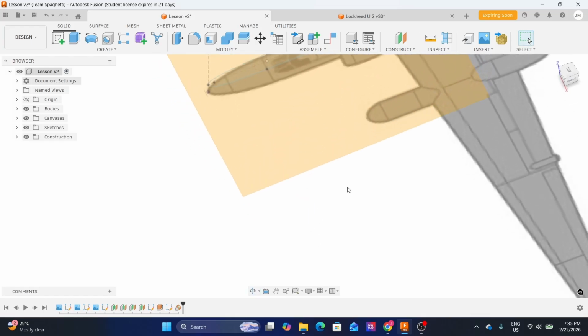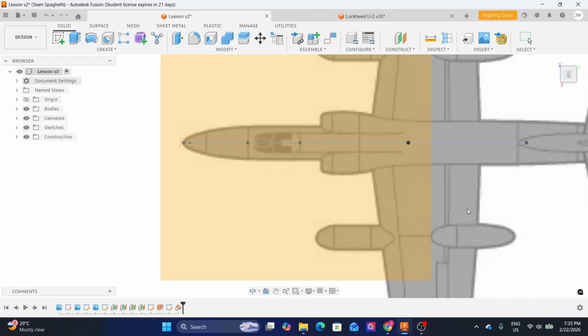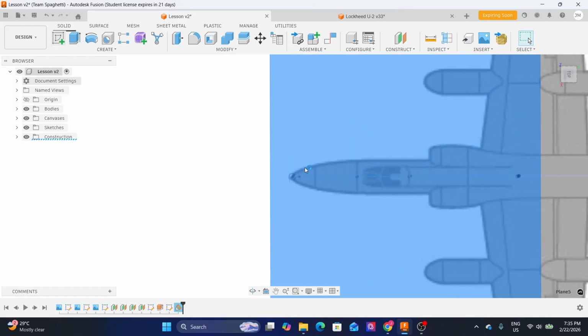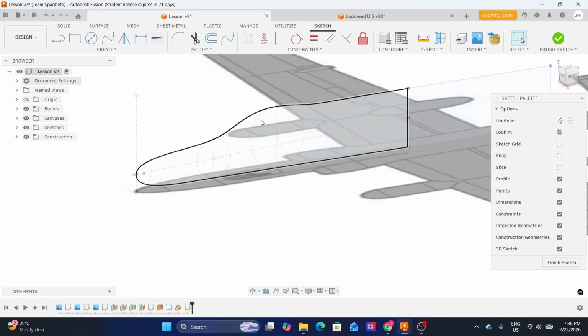Now we could start creating our top sketch for our top canvas here. So I'll select the plane again and then create sketch. Same as what we did here at the side canvas, we will project the 3D body, create construction lines, construction circles. We'll be using the fit point spline and also adjusting the tangent handles at the points of the fit point spline that we just created.